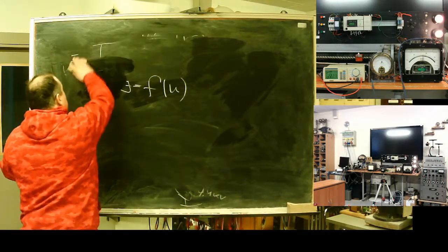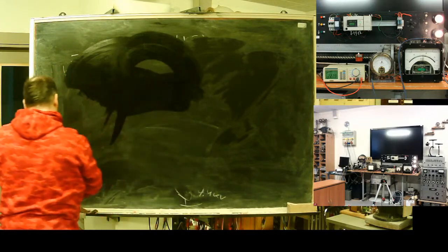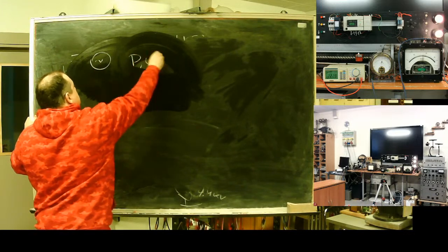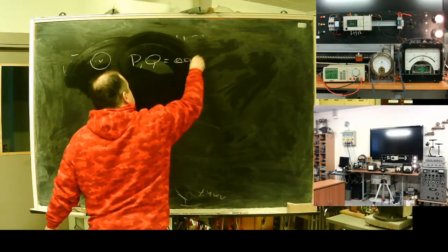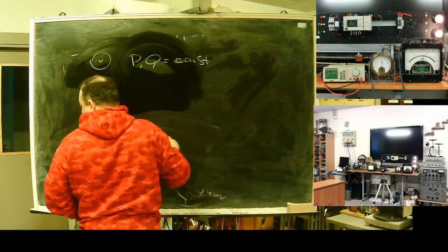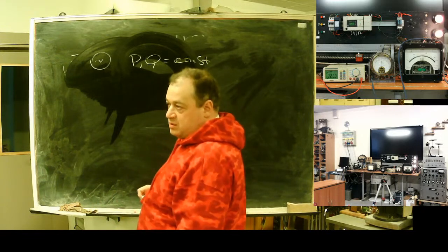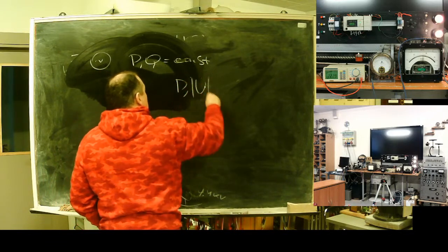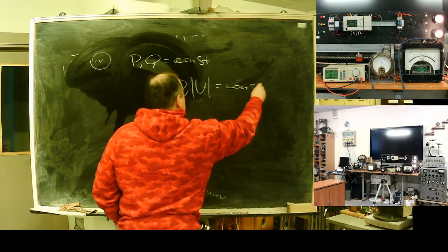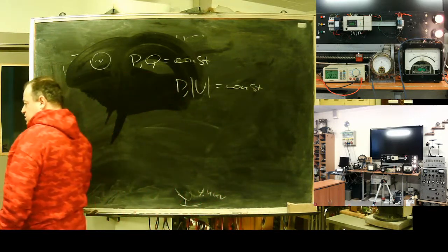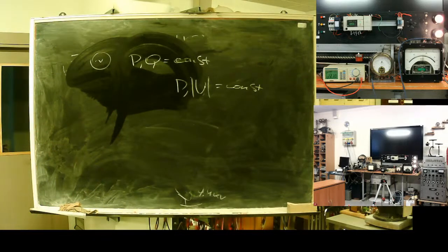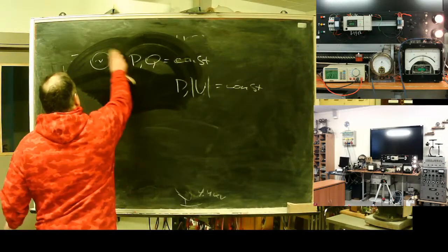Let's assume a simple model. Let's assume that generators also work with constant value. There are different control scenarios, maybe P and Q constant, maybe P and U constant. We can reflect any of them. I just take constant power, to make it more visible, just for simplicity.